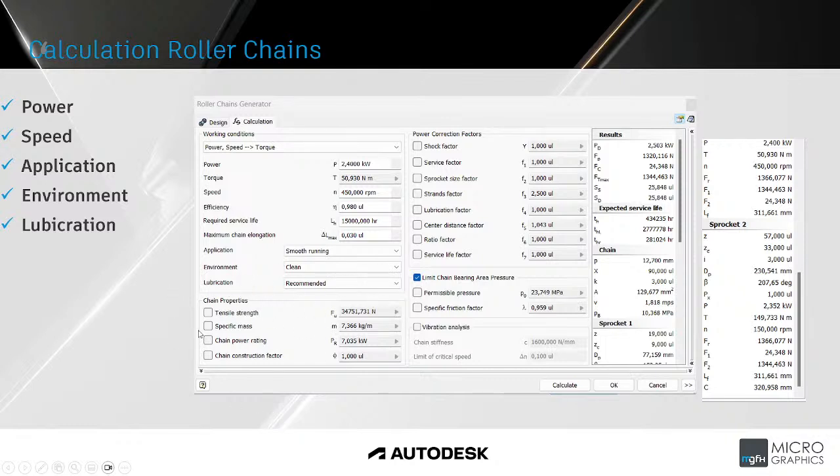So with the chain properties, I didn't add anything specific here, or with the power correction factors. And I ran the simulation and I calculated it. So Inventor ran the calculation for us. As you can see with the results, it's quite nice because it can actually go up to 2.5 kilowatts. So that's also quite a nice and handy tool to have with the calculation.